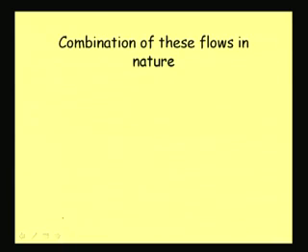Now, when we name a flow, whether we can call a particular flow steady flow, will it be sufficient, or if we say a particular flow is uniform flow, will it really represent what the flow is? Definitely not, because when we talk in terms of variation, we need to say how it is behaving with respect to space as well as time.